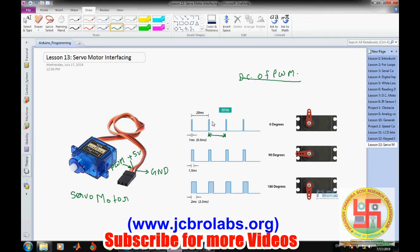Now within that time duration of 20 millisecond, the pulse width is minimum 1 millisecond, which is required to put the motor at 0 degree. If it is less than 1 millisecond, it will remain at 0 degree. So these are conditions for a general motor. Obviously these specifications sometimes vary from manufacturer to manufacturer. For instance, some manufacturer takes 0.5 millisecond pulse duration to keep it at 0 degree.